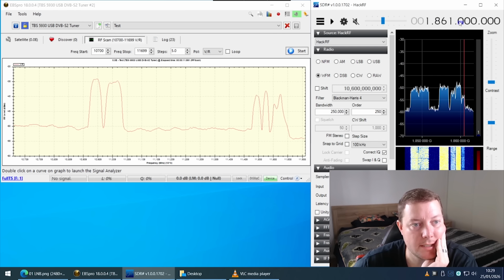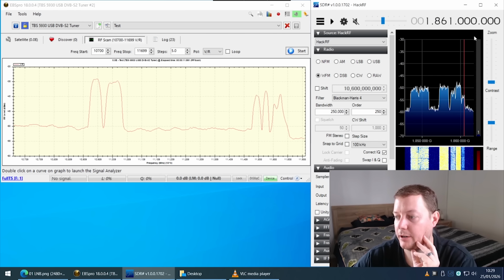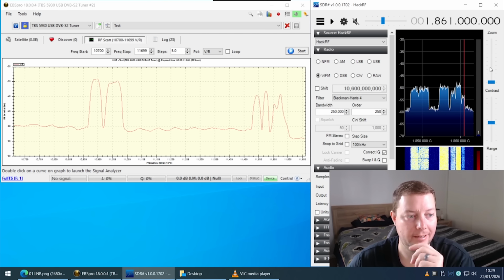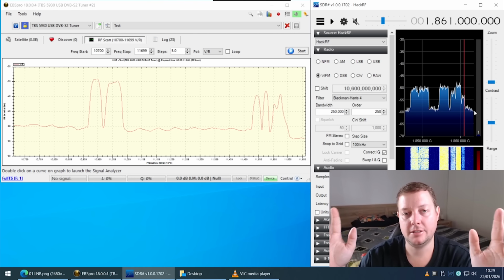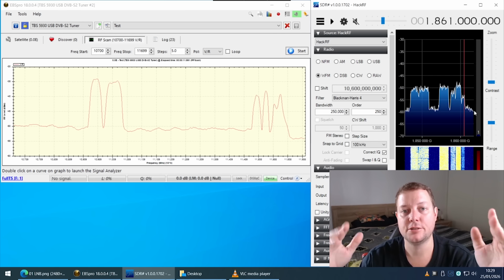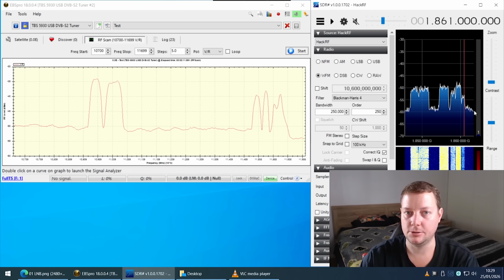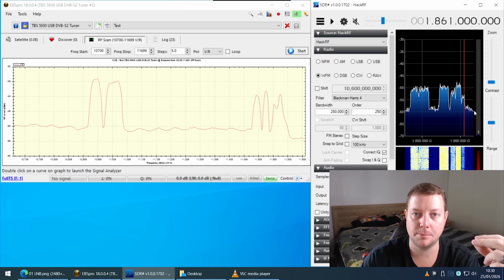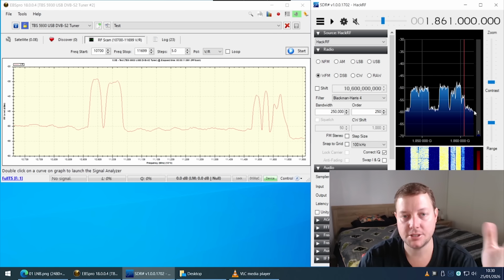Now this is a single channel per carrier feed channel. Okay, so this AMSAT DVB-S demodulator is very limited, right? You'd be lucky to receive any more than maybe 5 megahertz wide DVB-S signals. You're just limited to USB bandwidth, the processing overhead load on your computer, that kind of stuff.